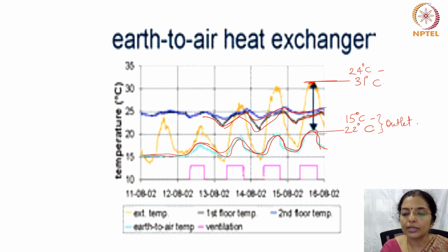So this can be the impact of earth air tunnels, and you can see how much energy savings can happen, because the load on the air conditioner will be completely cut sometimes, and sometimes dramatically reduced, because the air temperature it has to handle is much less than the outside air temperature.